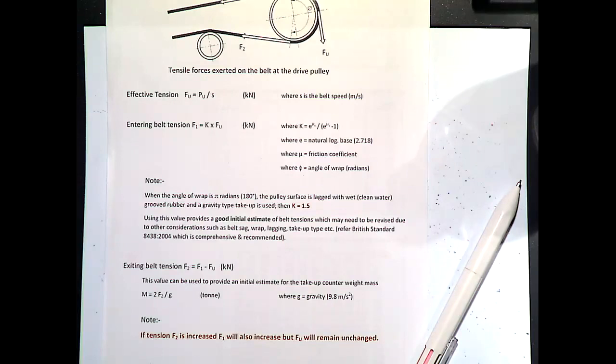Okay, design consideration. Quickly, sometimes they get a bit worried about the belt getting jammed up there, so they do this. But then this means that it's unidirectional. If you go this way, you'll be right. If you come this way, you'll steer the belt off and you'll have it on the ground. So there's problems there. That's in a mine. They actually suspend all their frames and idlers and stuff from the roof.